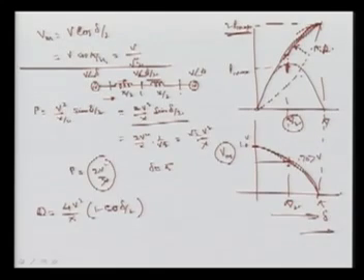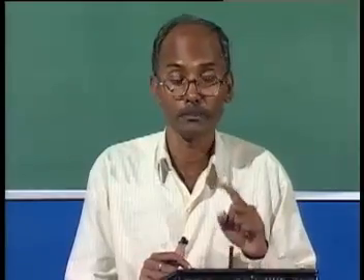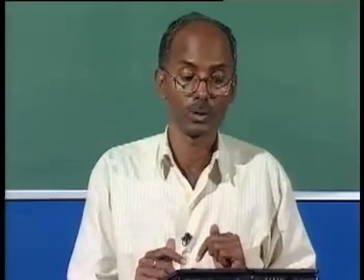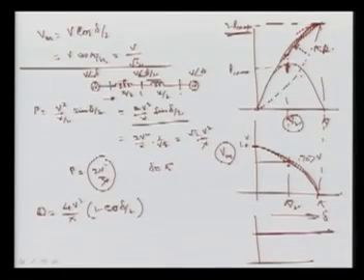So here I want to tell you that by maintaining the voltage, what will be the midpoint voltage? We are maintaining it at V, constant. So if you maintain the voltages in the transmission line at equal intervals, what will happen? We can transmit more power. So this is the beauty of your FACTS controller. And then I can see here your steady state limit is improved.